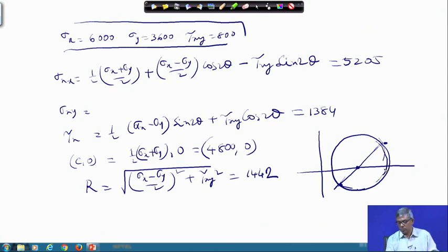Okay. So, once you get this circle, from this circle I can find out. I have to find out first this, corresponding to theta equal to 20 degrees. So, I can take theta equal to 40 degrees from here. From here I will rotate 40 degrees, I will draw a plane, and then it will be intersecting here. I will read this value, that gives you ultimately, based on the calculation whatever we have got, we may get the same thing from the graphical method also.